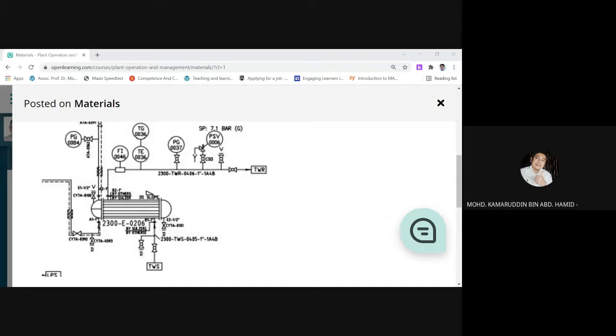If there is vapor formed here, then the first safety equipment that you have over here is the PSV. PSV will release or vent some of the vapor. Buang macam tu saja sebab it's water. Tapi rugilah nanti, but it's okay because the safety is more important rather than losing some material.